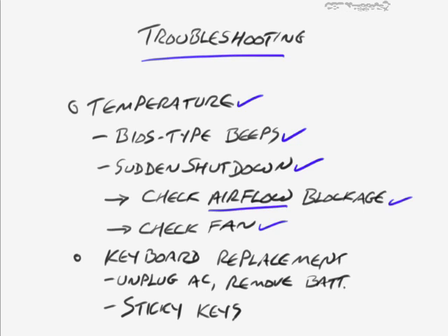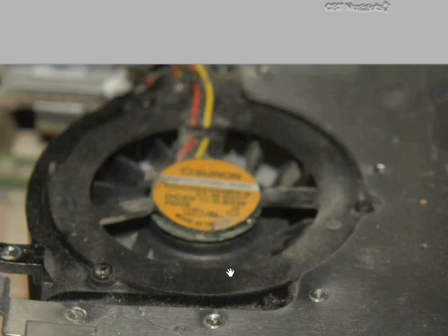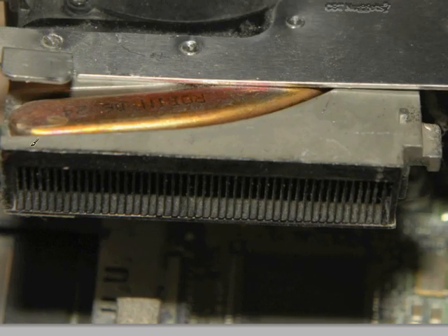Now, when it comes to airflow blockage, let me go back to this thing. This is normally on the outside edge. In this particular laptop, it's the left side of the laptop towards the back, towards the hinge of the LCD monitor. If a user is working in bed, a lot of people watch TV, or maybe they've got blankets covering this whole thing up, and airflow is not properly flowing through here, or it's being blocked, then that could certainly cause a problem.